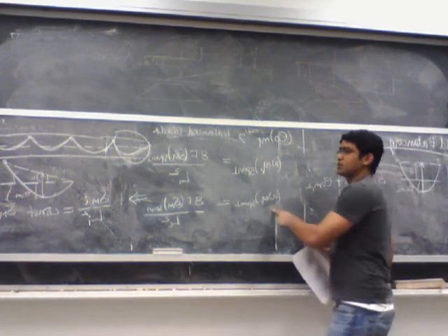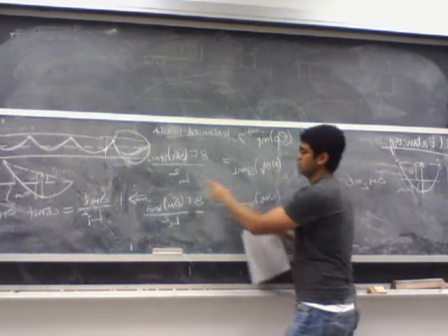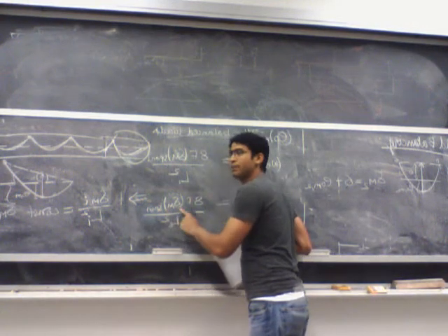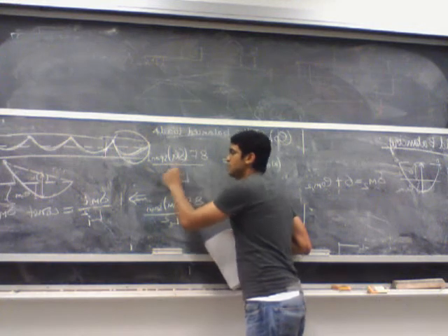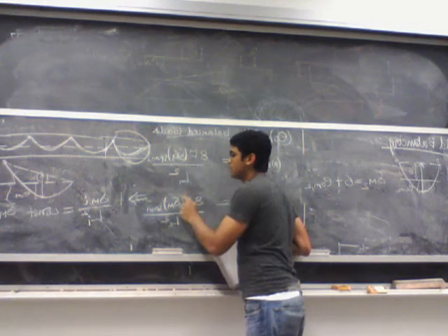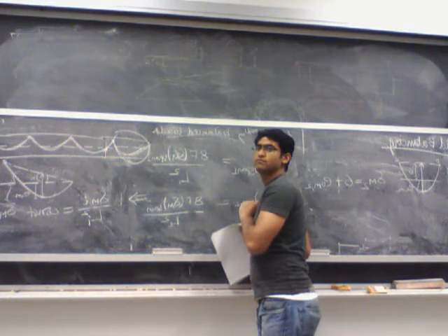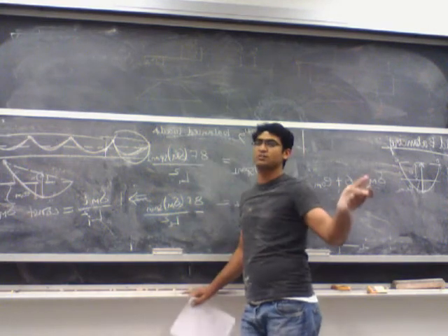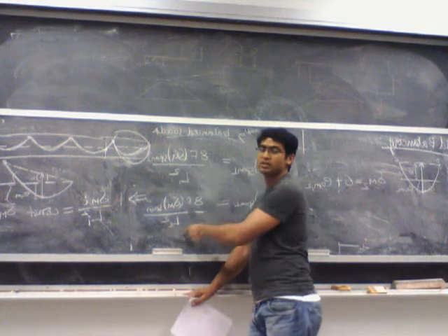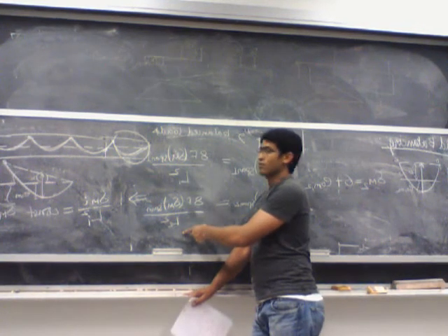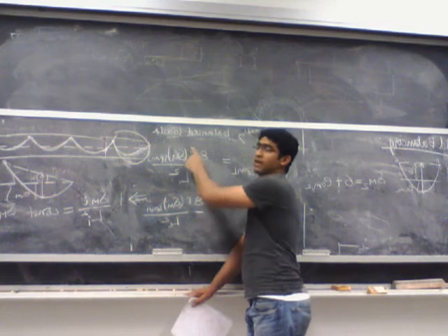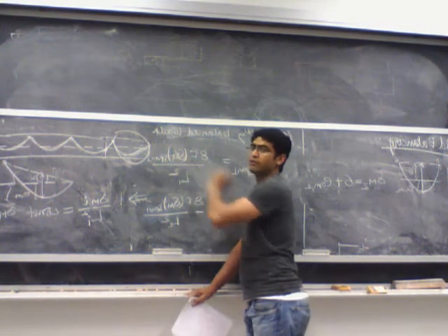So I go back to this equation. This is a constant value, this is a constant value. I know what is the maximum allowable for each one of them, delta m, right? So if I maximize this, what you are trying to do is you are minimizing the value of f, right? Because the multiplication of f times delta m has to be constant for each of the spans, if L is the constant for both of them. So what you want to do is you always want to minimize the value of f. That means you want to maximize the value of delta m.